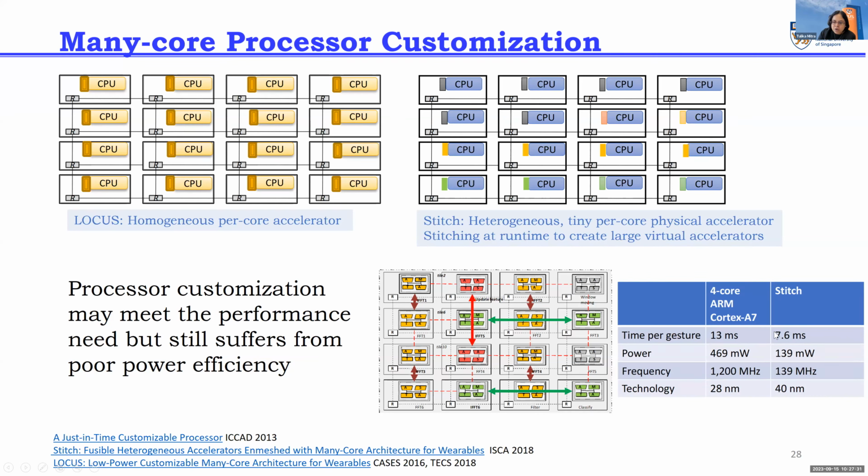So if you think about moving from specialized ICs that I showed you earlier to the microprocessor, now we are saying: can we have a universal accelerator that can accelerate all the different applications, instead of having these specialized accelerators? Their performance and energy efficiency should be closer to a domain-specific accelerator. Of course, it would not be as good as a domain-specific accelerator because it's supporting multiple different things, but it should be closer to that. And that's where the coarse-grained reconfigurable array, or CGRA, comes in. It is the most promising realization of that software-defined hardware vision.